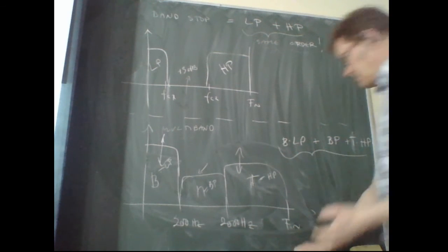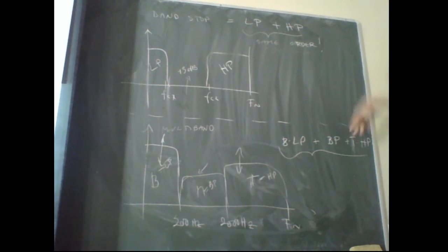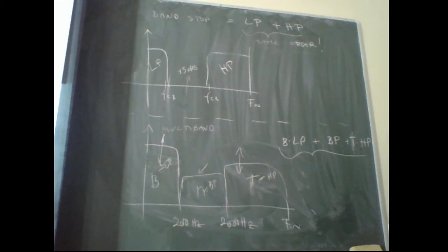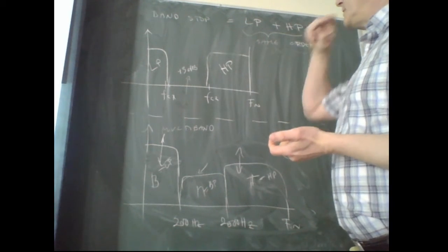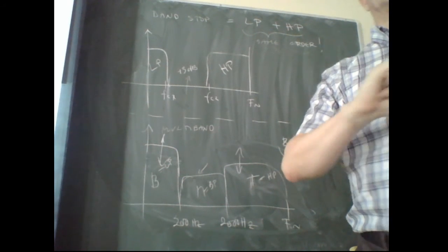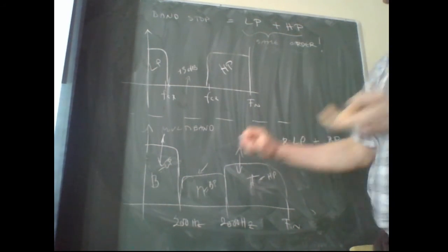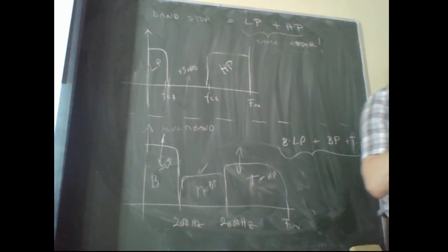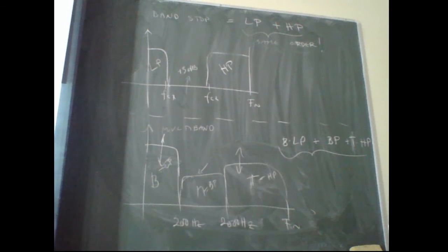So, that's maybe another reason to work with the FIR systems. But as I said, with IIR systems you get better amplitude response at the cost of nonlinear phase response, of course, with fewer parameters, fewer coefficients. Okay.